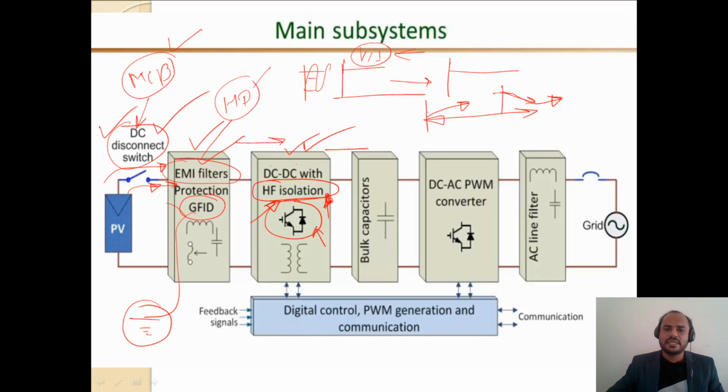Again, the power is given to the capacitor. The capacitors are DC link electrolytic capacitors we are using over here. When we open the string inverter, we found up to 20% of the area is covered by the capacitors only. The main role of the capacitor is what?